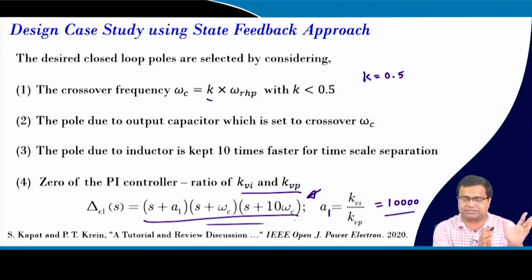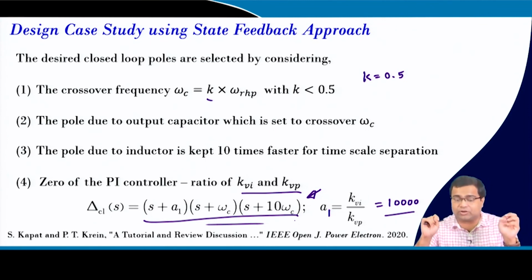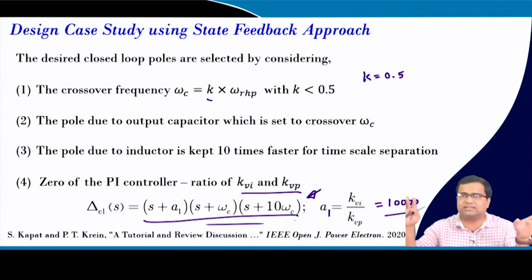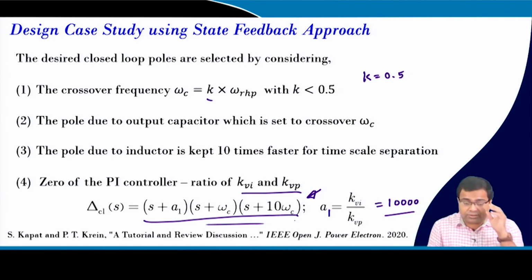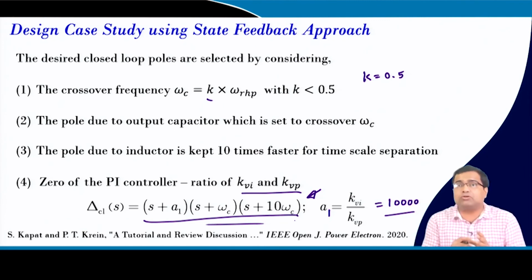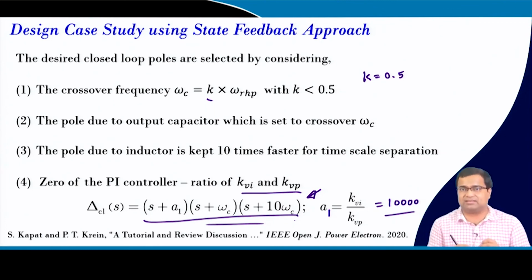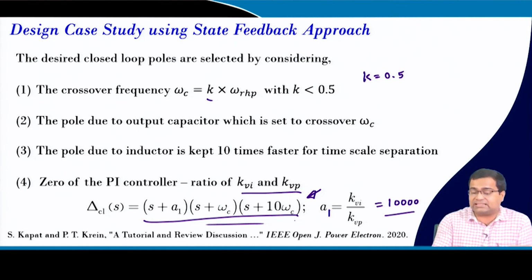Even for buck you can try it out, but for boost you can manage very well, because of the RHP0 we had a constraint in output feedback. If you wanted to increase the bandwidth, then your phase margin was affected, but here there is almost no overshoot. So, it responds nicely. If you go to digital control, in real time tuning you can easily incorporate the current loop gain. And in that way this approach can be very useful for digital control, current mode control design.